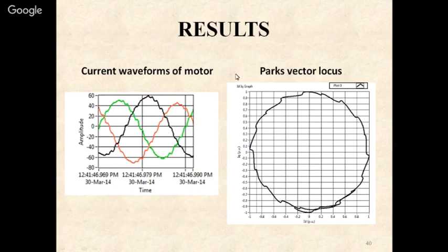By analyzing the motor currents from ABB, we have seen that the Park's vector circle is showing some features of high frequency content in the current. These may be caused by some load pulsation or by some fault. So we have to basically separate whether it is being caused by load pulsation or by the occurrence of some fault.